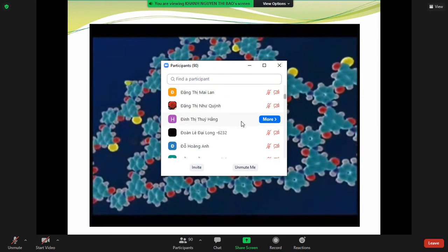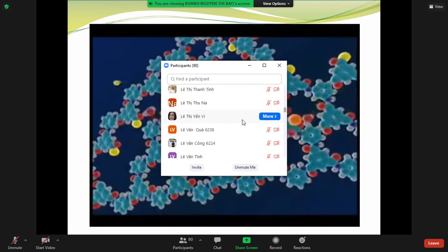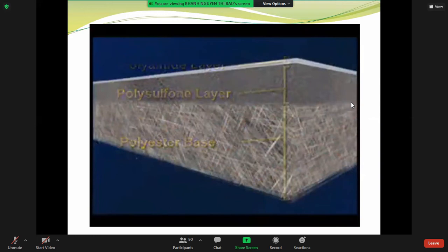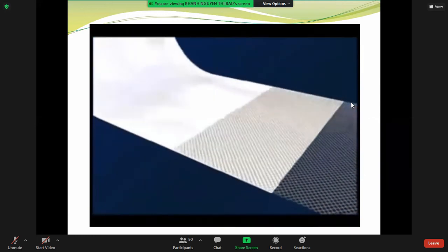Hydronautics manufacturing procedure enables independent optimization of the distinct properties of the membrane support and salt-rejecting skin. The combination of these three layers makes a durable membrane flat sheet that is used in each spiral wound element.